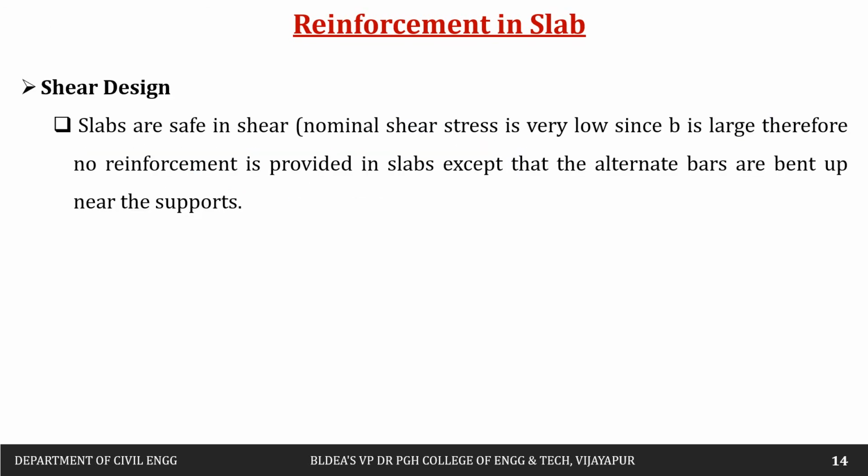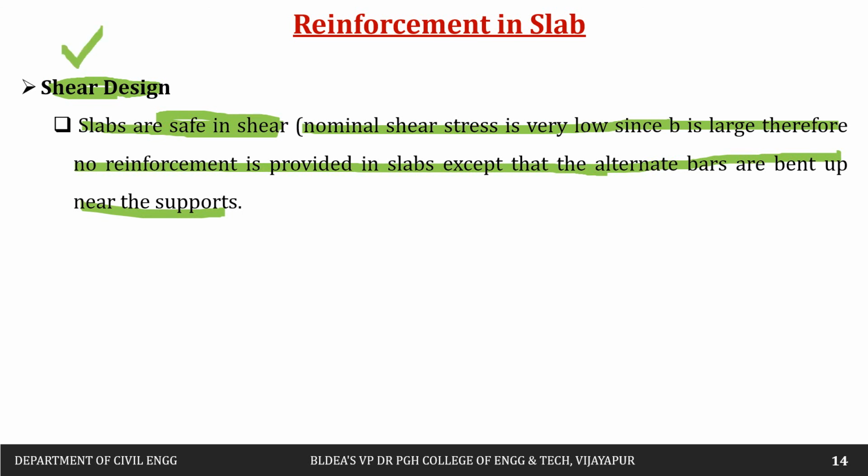Then next is regarding the shear design. Already I had said, once again I repeat, slabs are safe in shear. Why? Since the nominal shear stress is very low, because the width is large, therefore no reinforcement is provided in the slab except that alternate bars are bent up near the supports. So in the slab design we don't provide shear reinforcement.